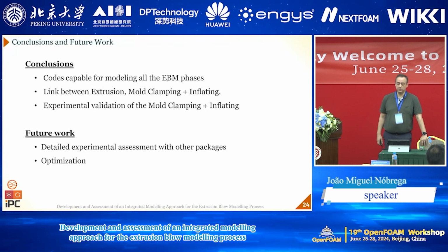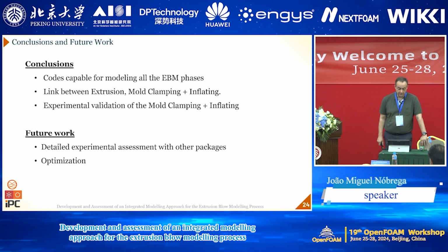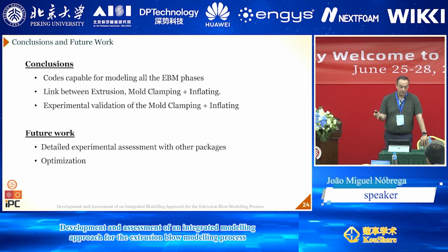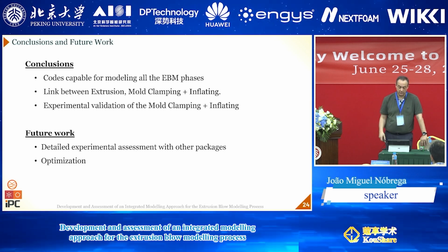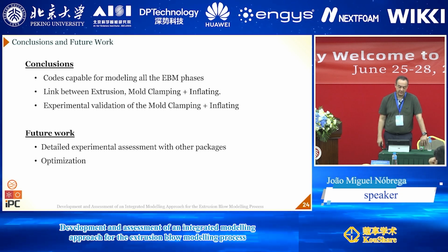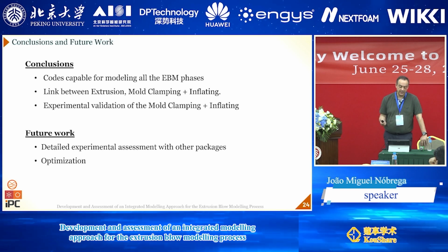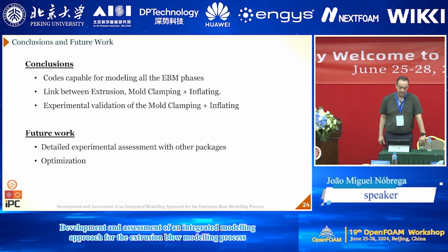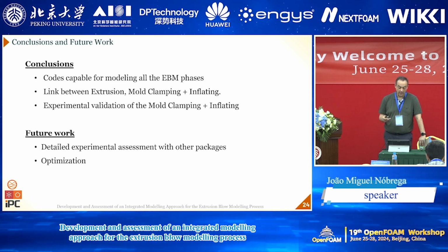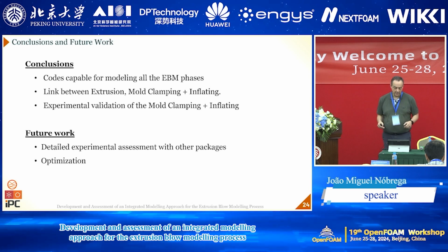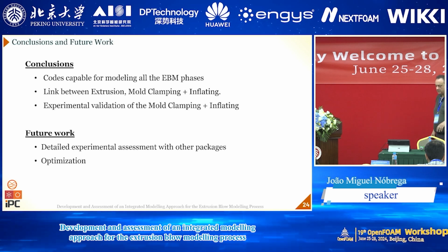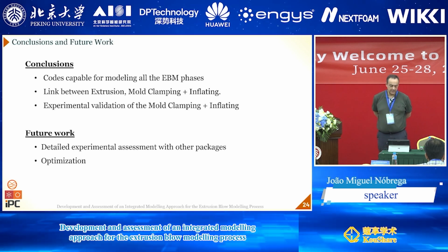So this takes me to the final conclusions of this presentation. I showed you the codes that are able to model all the process. We have already the link between the different phases, and we validated the mold clamping and inflating phase, which shows us that the solvers we have give, at least for this case, quite accurate results.